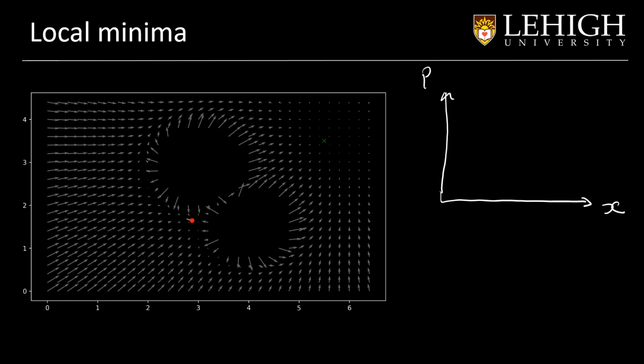This is the potential, and the function of the potential will have this shape, where our goal will be here. If the robot starts here, the initial Q will be here, it will go down without any problem. But if the robot starts here, it will fall into a local minima, and this will prevent the robot to go towards the goal. That's the main limitation of this method.